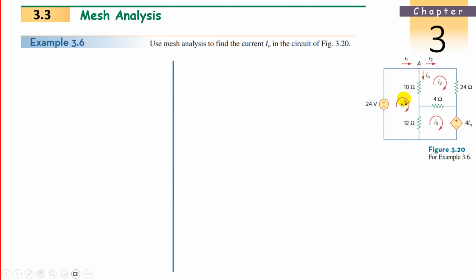So he only mentioned what is the I0. No need to name the current there again. Okay. Now we can name other branches. So the voltage source, the current is I1. This resistance 24 ohms, current I2 I am assuming, and this one current I3. Okay, 3 loops are there, but one problem is here. What is that? This 2 resistors. This is correct only. This is a loop current, so small I1. This is a loop current, small I2, and this is a loop current, small I3. No problem. You can go ahead.